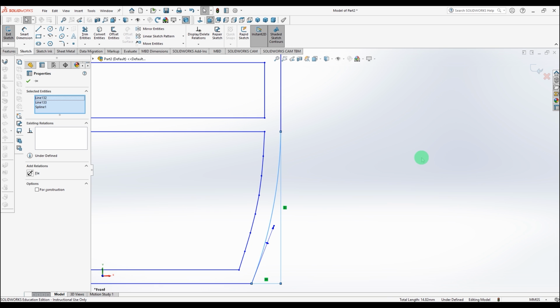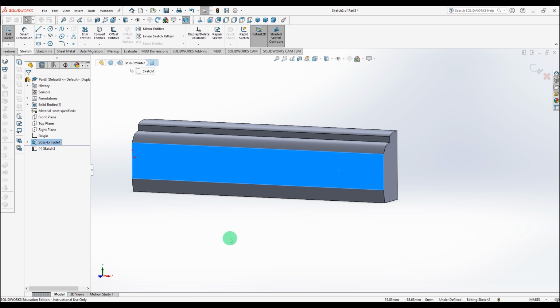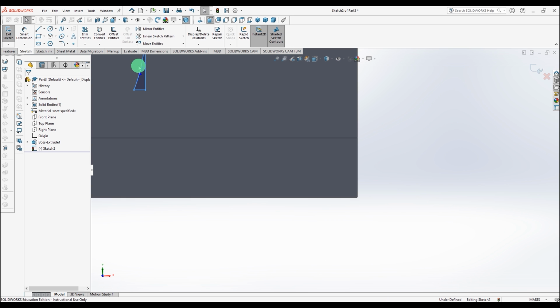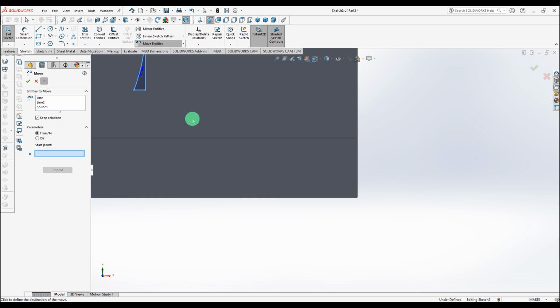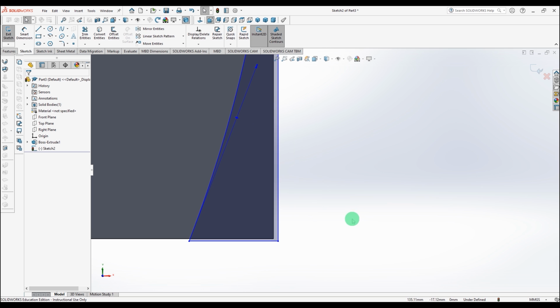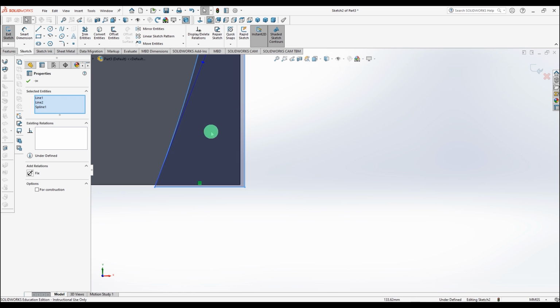So I'm doing my final tweaks and bits and pieces here. I've copied that. We'll come into here, we'll select that side face. We're going to create a new sketch, and then I'm just going to Control V and paste my little triangular piece that I'd created, and we'll drag that over and stick it on the corner there, and you can hopefully see how that's the bit that we're going to extrude, do an extruded cut. We're going to slice off, but of course first it's necessary to get it properly aligned.